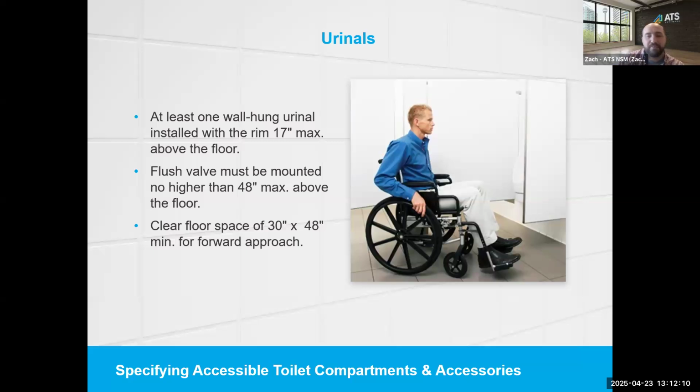And on that same point, you referenced it there when you said the wall or the panel. So for the sidewall grab bars, especially when you have a toilet tissue dispenser behind the sidewall grab bar, as we showed in the image, have you had AHJs that object to the thickness of the flange and that flange encroaching on the 1.5 inch distance? Is it the distance from the toilet tissue dispenser? Or is the issue the distance from, say, the partition or the wall?